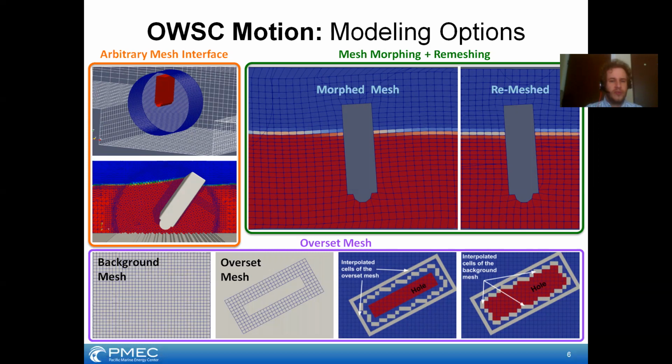But the nuts and bolts of actually doing the fluid structure interaction can typically be done in 3 different ways in OpenFOAM and in general in CFD software. The first is the arbitrary mesh interface approach used by the paper authors. And this involves having a separate region of the domain that slips or slides inside an outside background mesh. So you can see here a cylinder is a natural choice for having something rotate, and the flap is encompassed by the cylinder.